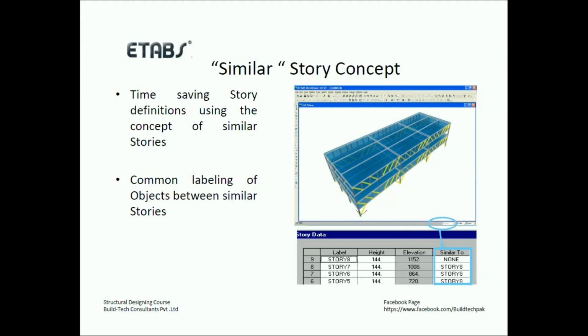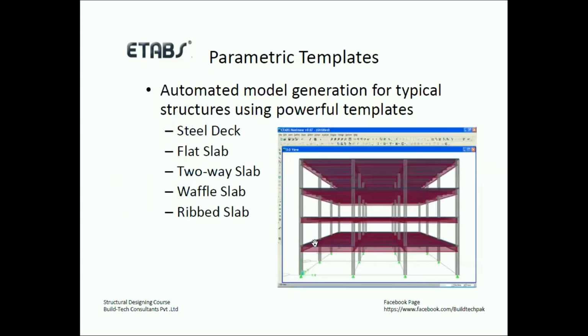So you can define in Etabs like three different यानी इस building के लिए जिसको मैं भी discuss कर रहा था कि जिसमें 30 stories हैं. So you can define three master stories. For example, मैं story number 1 को master story कहूँगा. And whatever I'm doing on master story 1, it will be replicated automatically story 1, 2, 3 up to story 10. So the second story that I will create, it is master story 11 से लेके वो फिर 20 तक सारों को एक जैसा ही मॉडल करना स्टार्ट करेगा. So this thing we will cover in next session as well.